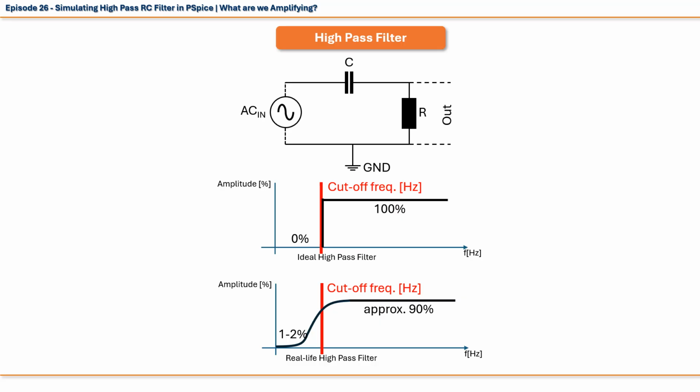For those who are new, a quick reminder: a high-pass RC filter is an electronic circuit containing a capacitor and a resistor in series, where the resistor is connected to the ground with one terminal. Its function is to eliminate undesired frequencies from an AC audio signal. Its main parameter is the cutoff frequency. Everything below the cutoff frequency gets attenuated, while the rest of the signal goes unchanged. One common real-life implementation of this circuit is dividing an audio signal for playback on a subwoofer and stereo speakers.